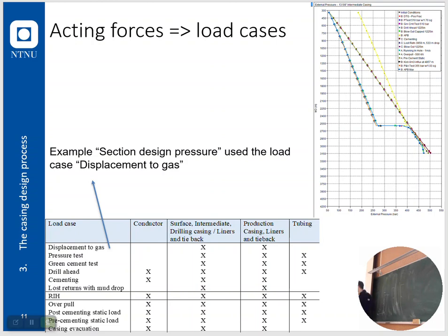Post-cementing static load, again, also the pre-cementing static load, both of them in the same category as drill ahead and cementing. They are not really demanding load cases. They could be in very, very special cases, so we have to do them. But so far, I have never seen them setting any precedent to what we should pressure test to.